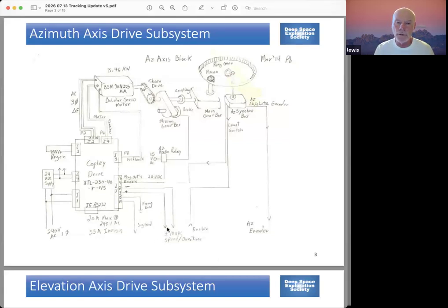It's a differential. I will say that right now the system one controller is not passing a true differential signal to it. And so it still works fine, but what you lose is the differential gives you noise immunity, but if you don't use it in that manner, then you don't get the benefit of the noise immunity.